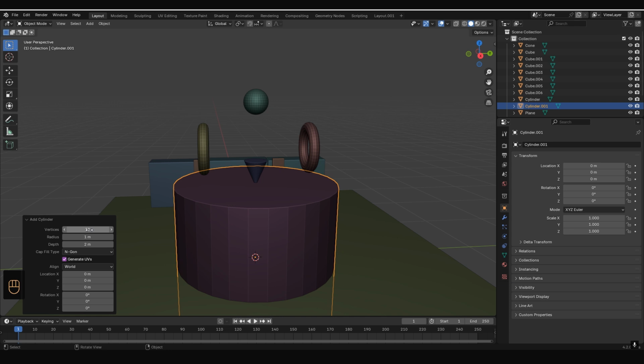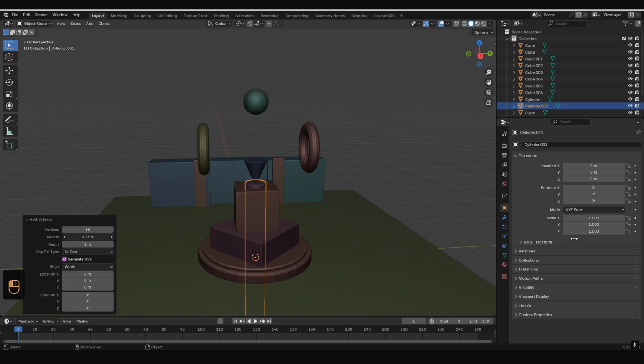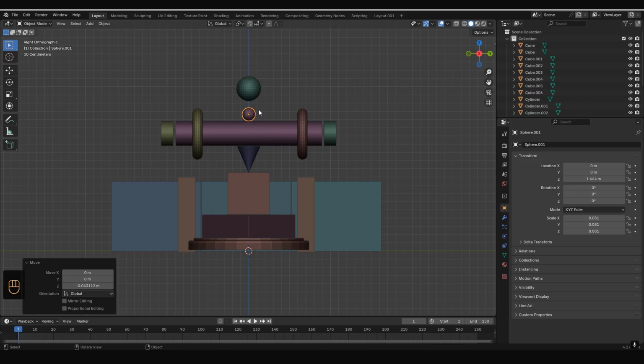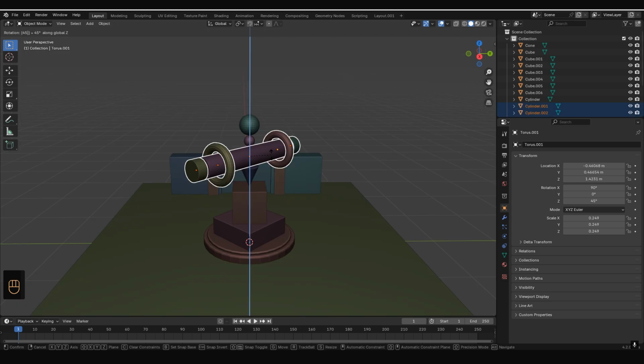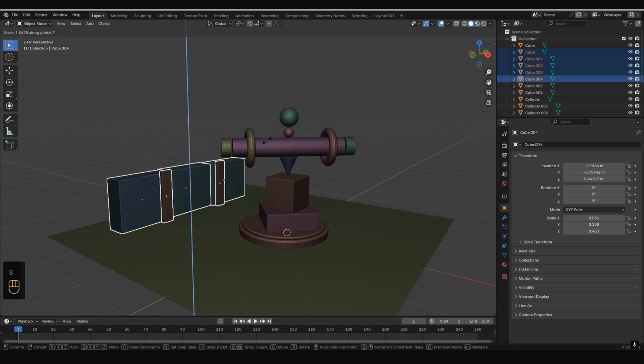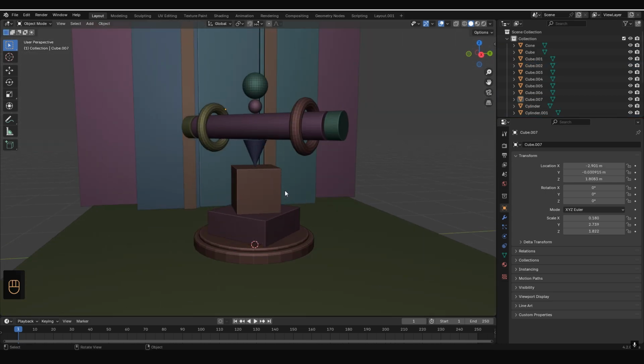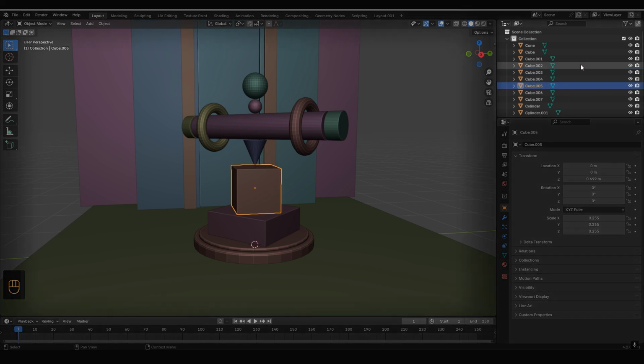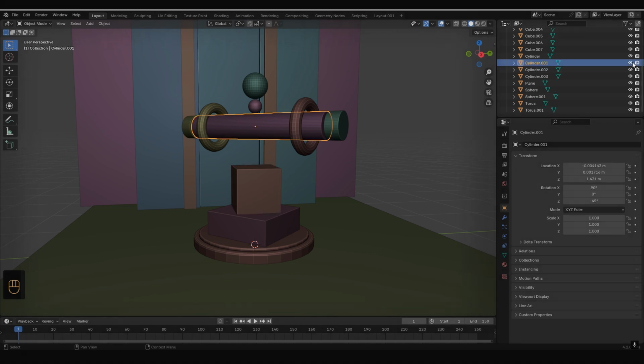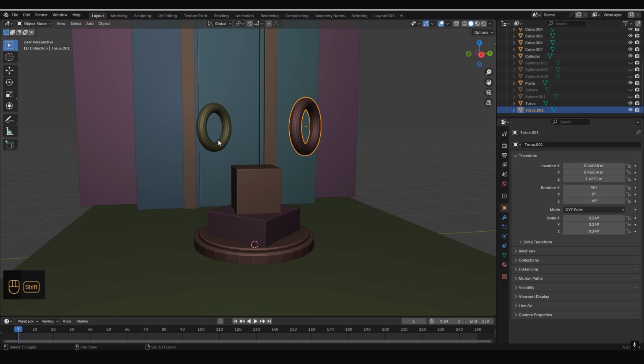After adding an object without deselecting it, you can customize the primitive in the lower left corner. Number of segments, radius, position, etc. The settings will remain available until you deselect the object. We can hide objects to keep them out of the way. In the Layers window on the right, click the eye next to the objects you want to hide. Use hotkeys H to hide and Alt plus H to show hidden objects.